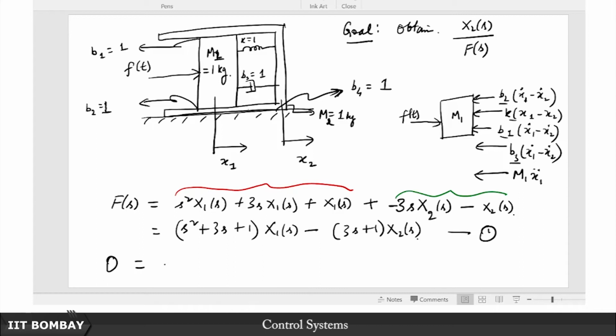So what I know as the coefficient of x1 will be nothing but what was the coefficient of x2 here, of course with a minus sign. So this is very obvious. What needs a little more thought is basically the coefficient of x2 in the equation for m2, just like we needed a bit of thought for the equation of I2 in the loop for the current 2, right. So here each loop corresponds to each mass element, okay. So let us see what comes in inside this. Whatever's the total ensemble connected to this mass m2. What is connected to m2? This is 1, this is s, right. There's this one s over here, one s over here, right, and there is another additional s which is unique.